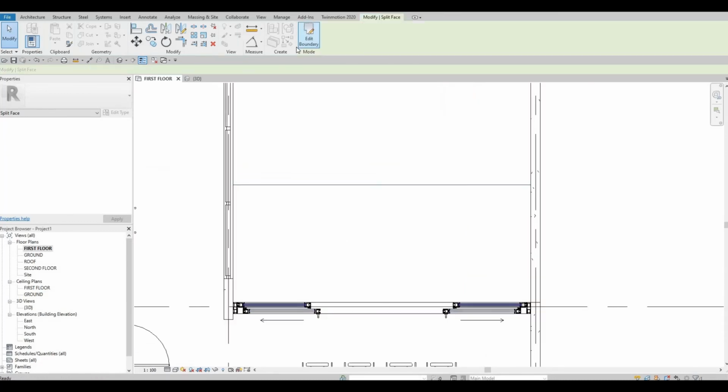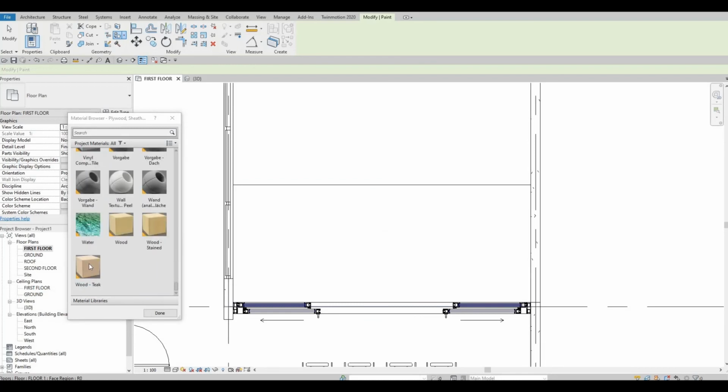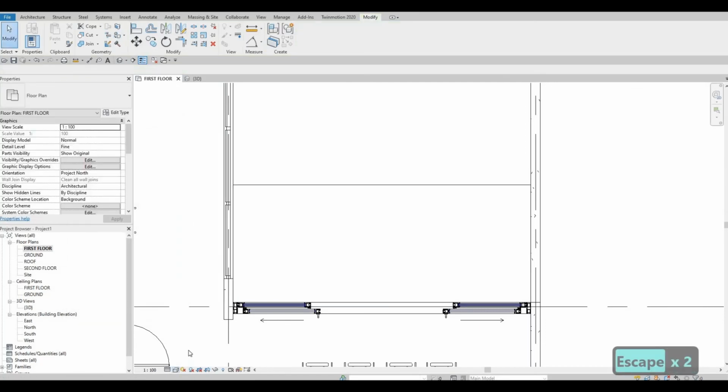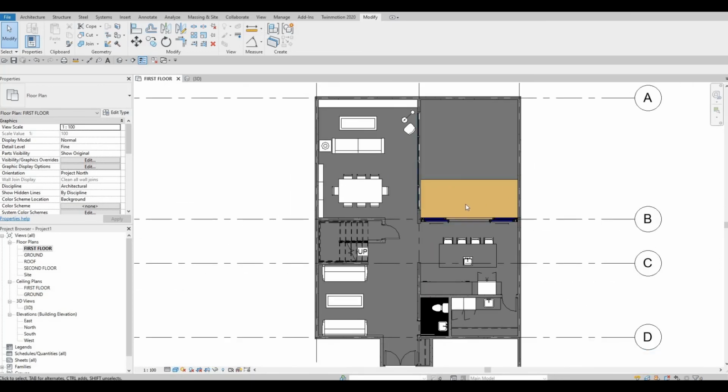And then now click finish, and then click on paint, and we're going to add a plywood sheet in here, but we're gonna do some different kinds of wood, maybe thick, so we can choose thick as well, but plywood sheeting for now. And then select that. You want to double check that, so just change this to consistent color, and then now you have something like this.